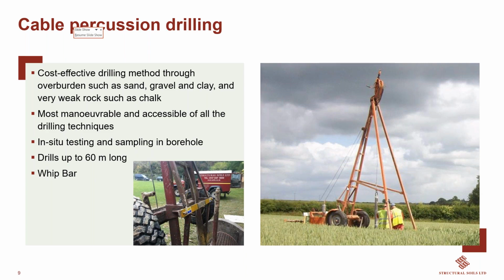add to this is that whenever you're on site, please ensure that the driller has these side stays on, and also it's mandatory from the British Drilling Association to have a whip restraining bar that is in operation at all times. This will prevent the rope from coming out and causing accidents with the driller. So that is a very important part. So again, if you do notice it that's not on, please ask your driller to please put that back on.